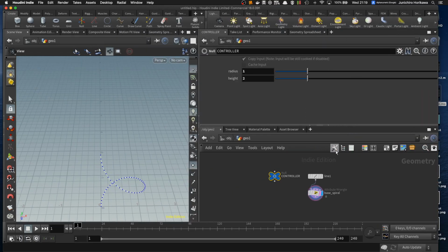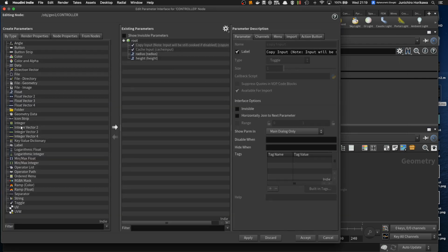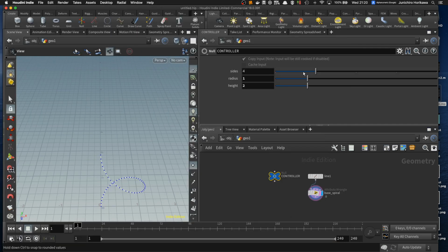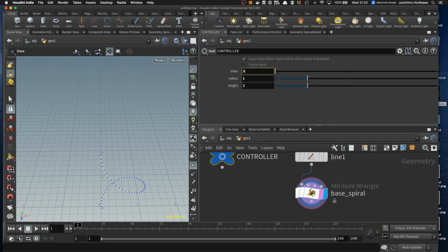So let's first go to the controller's parameter interface and then make an integer parameter called a size to indicate the number of sides, maybe starting from 3 to something like 7 or 10, anything. If you make the number of sides high, then the geometry will become smoother and smoother. Right, then let's start with this 3 and copy this parameter to...